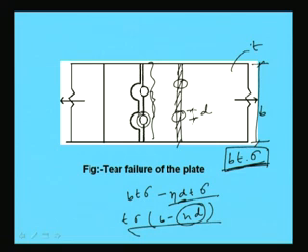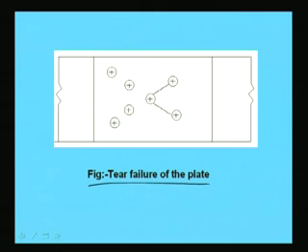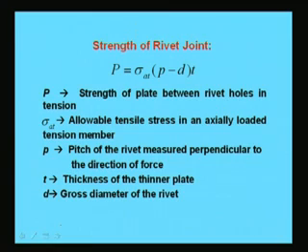So, failure may happen because of different reasons. One is failure of the rivet itself, another is failure of the plate at that position, that means through that section. So, this tearing happens because of the presence of the rivet hole. So, the efficiency of the joint will decrease if we increase the number of rivet holes, from the tearing point of view, right. So, another chance of failure will be this tearing failure when it is zigzag, that also may fail, which is very unlikely. The tearing may happen like this, though it is very unlikely, this type of failure also may come into picture.